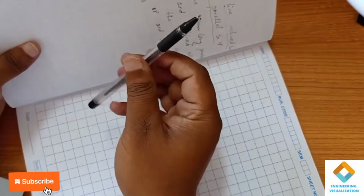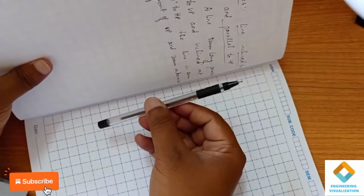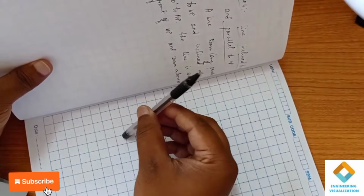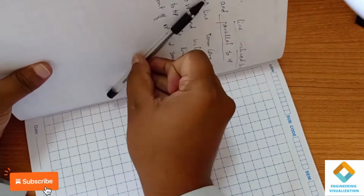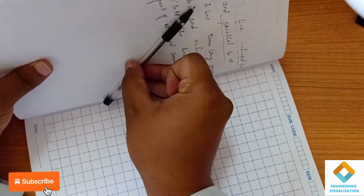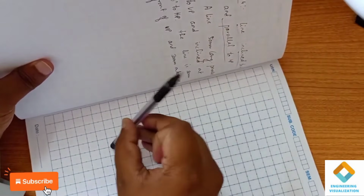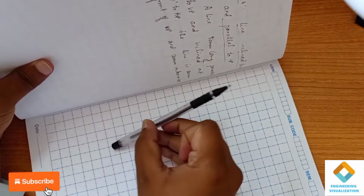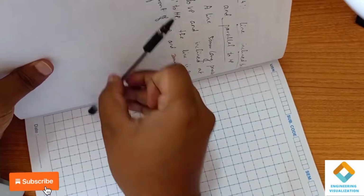You can see this is parallel to the VP, but here there is inclination from the HP plane. It is inclined to the HP and parallel to the VP. Parallel to the VP means we get a straight line. Inclination to HP means either 30 degree, 45 degree, 90 degree. So this is the inclination to HP and parallel to VP.